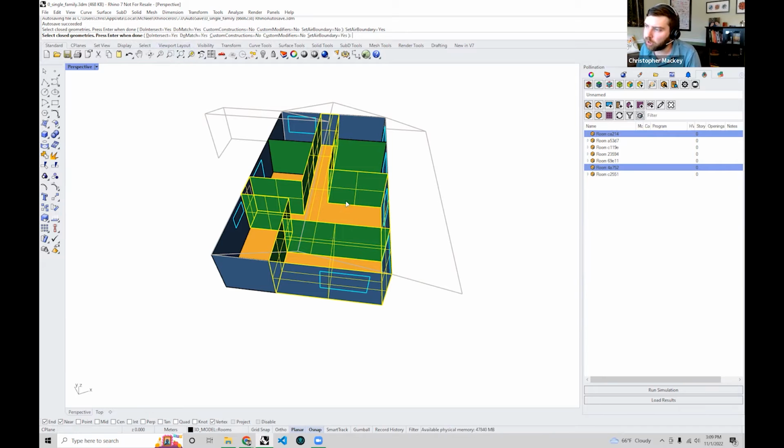Maybe if you are going to use air boundary after solving adjacency initially, I like to turn the intersection off, because there's no real need to redo the intersection, and this will make sure that none of the IDs of the rooms or the actual faces get changed in the process.